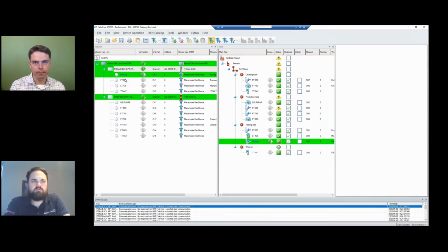We've got a question from Fortunate. It asks, is it possible to access field HART devices through the gateway? And do you need a special card to access HART data from the device? So yes, on the gateway side, as you can see here, there are no driver files for directly configuring a device. So we need a client to access through the gateway. If there's a restriction on machines or clients, we can virtualize the whole thing. We can have one computer there that has a virtual machine for the server and a virtual machine for the client. That's possible, but you need a client to access that, as in any client server system.